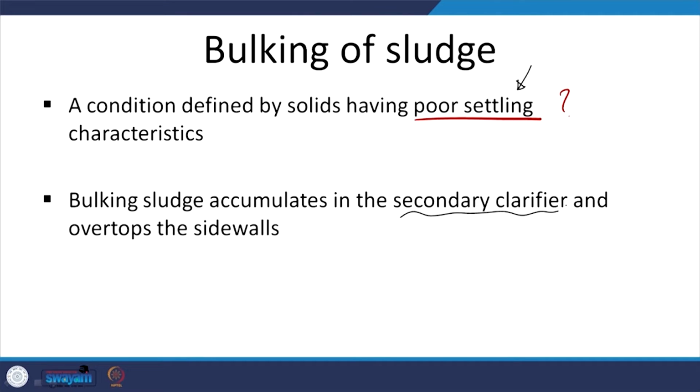And sometimes the situation is so severe that it can overflow. Again, there are different kinds, but as I mentioned, different sources mix different aspects. One is sludge bulking, and in the way that we looked at it, we encompass most of the kinds of issues with sludge settling within bulking, but different sources distinguish between bulking, viscous bulking, and then foaming. So let's have a quick recap of these aspects.